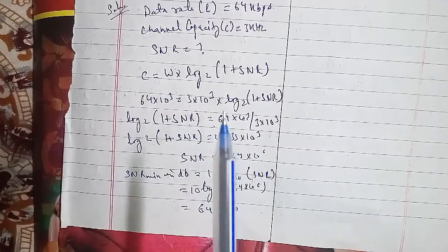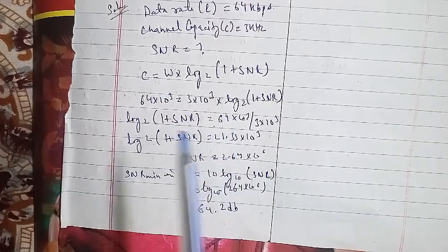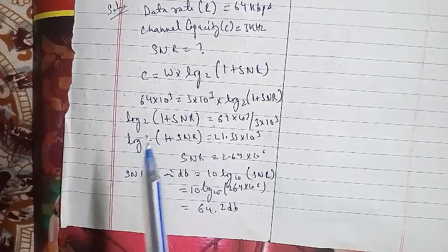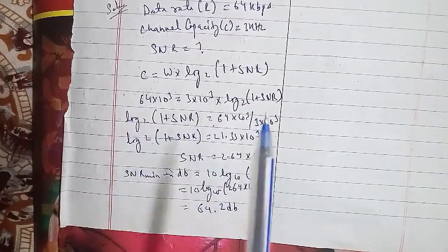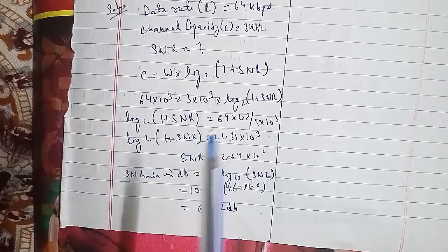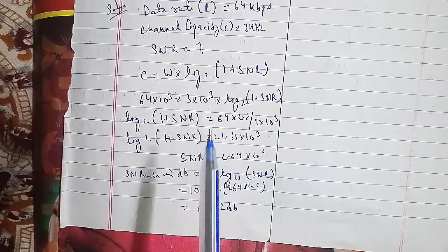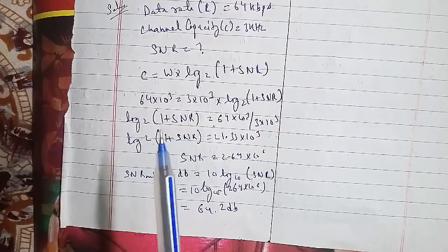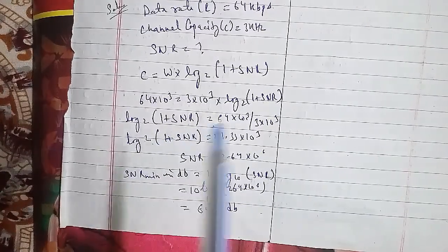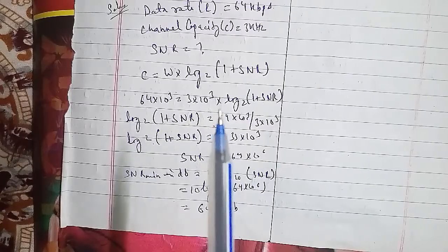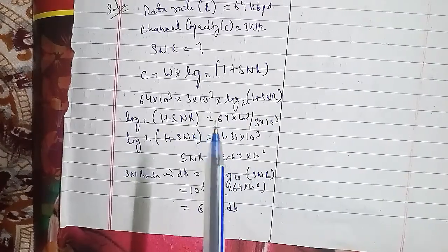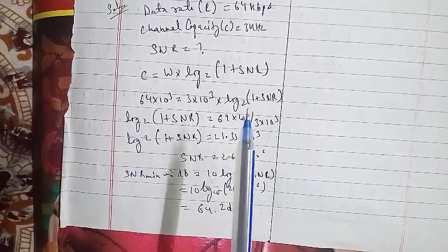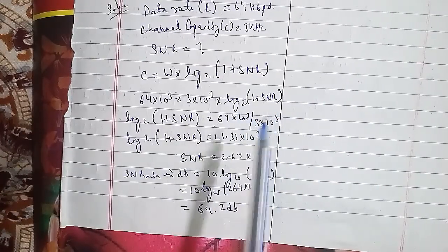Delay distortion is critical in digital data, and it causes intersymbol interference. Hence, the maximum bit rate for the channel is reduced. Delay distortion is caused by the fact that the velocity of propagation of a signal through a cable is different for different frequencies. For a signal with a given bandwidth, the velocity tends to be highest near the center frequency of the signal and falls off towards the two edges of the band, and thus the various components of the signal will arrive at the receiver at different times.